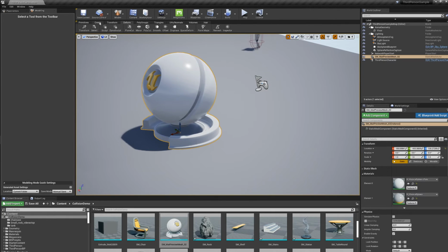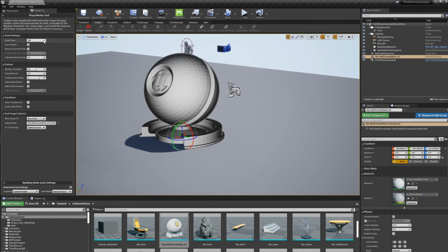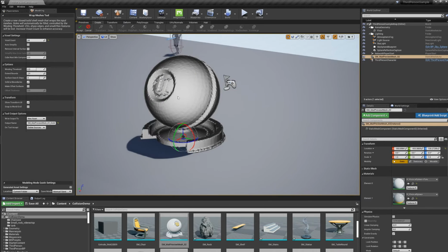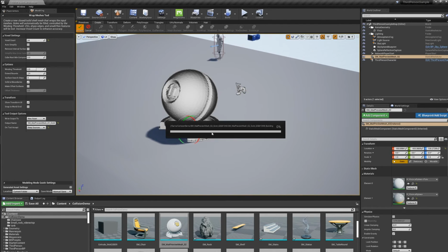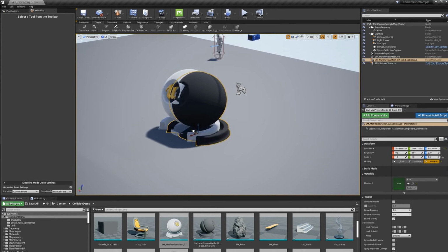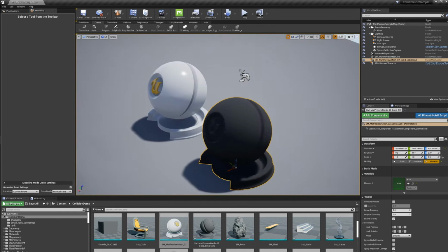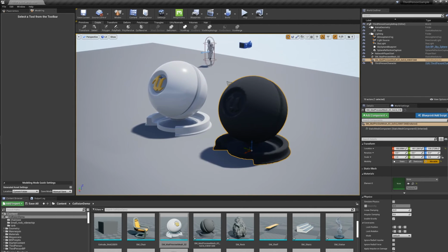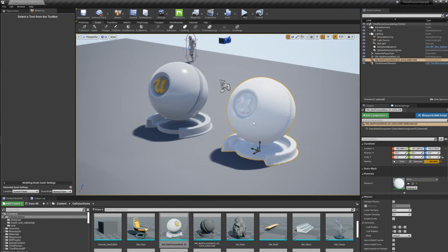And then I'm going to use that. So what I'm going to do first is go to the Create tab and do this VoxWrap operation, which is a little expensive. I'm going to turn this down to 64 just so it's faster. But what this does is it basically voxelizes the whole thing. I'm going to set down here, instead of deleting sources, I want to keep them. And I'm just going to accept that. So that's going to make a new asset. Right, there's the asset. It's very dark in this lighting, but it's essentially the voxelized version of this. I guess we could set this to my white material so that it's clear to see.